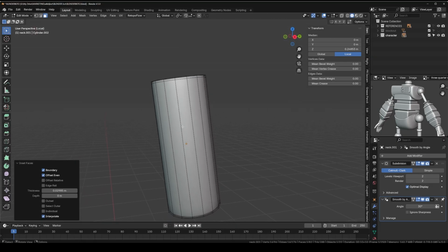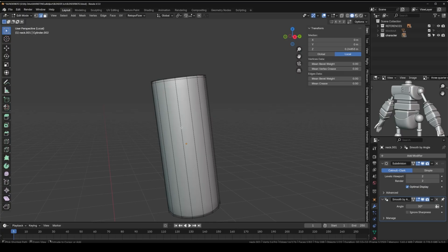So I'm going to edge select mode, I'm going to press Control R, and then before you click it, just scroll your mouse wheel and then you get more. So I've got 3, 4, 5, 6, maybe I have 6, and then just click. And if you click it once, you can still move it, and then if you click it again, it's confirmed and it's there.